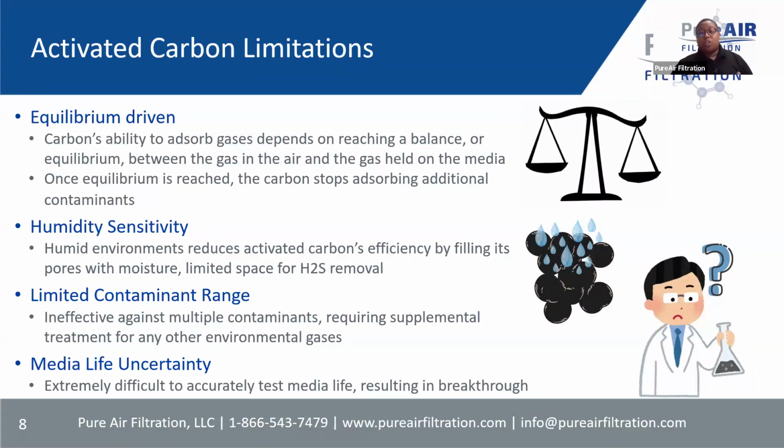When the carbon reaches moisture saturation, it's possible that it can even release some of the previously absorbed gases. And this is what makes that absorption process a reversible process. This will compromise air quality, of course, and requires more frequent media replacement. So it becomes more costly over time.